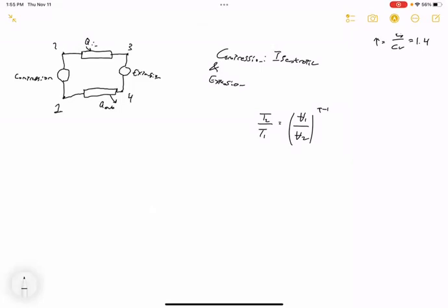In other words, what this tells us is that temperature increases when the volume decreases, which kind of makes sense because we know about ideal gases, PV equals mRT, right? This makes sense, but this is just in the case of an isentropic process, it doesn't just decrease in any way. It decreases specifically V1 over V2 to the power of 1.4 minus 1 if it's air, gamma minus 1 in general. So this is the first of three relations we're going to need to keep in mind.